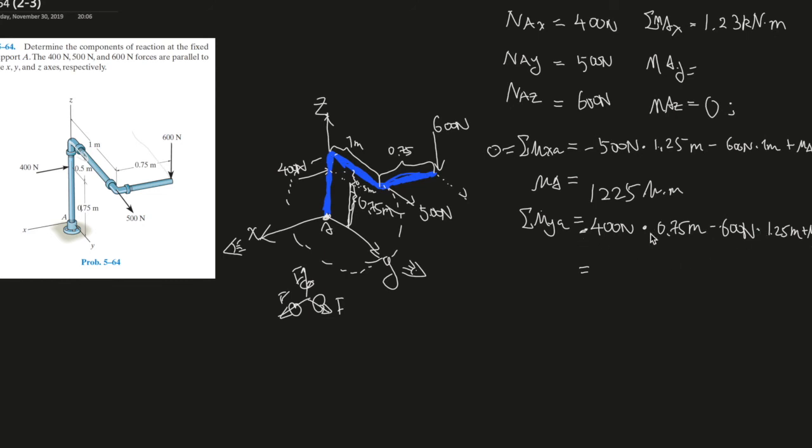So moving all of this big chunk of numbers to the left side, anyway, this is equal to 0 as well, right? Set this to this side, and the moment on the y-axis, if you plug everything into a calculator, should give you 750 Newton meters, and that's it, right? You can highlight your answer, but this is well organized, so we can leave it like that.